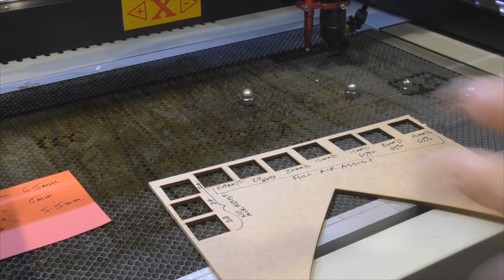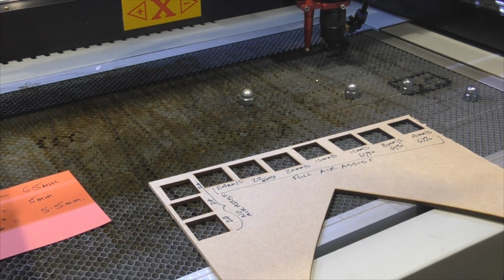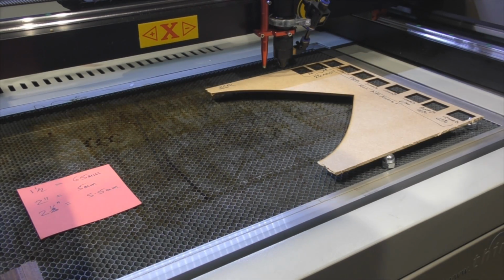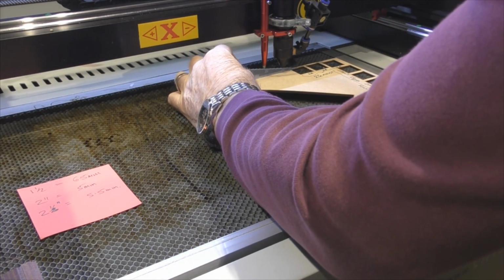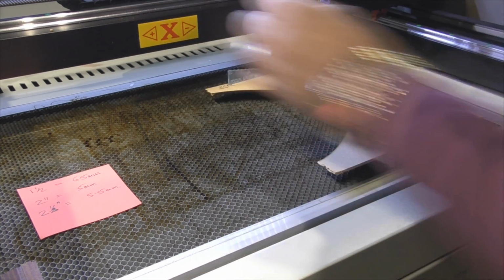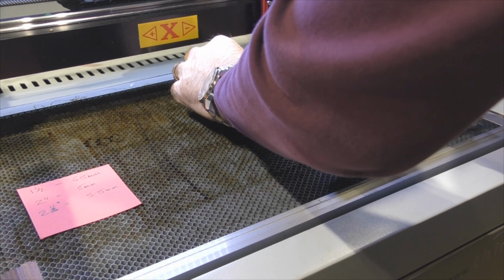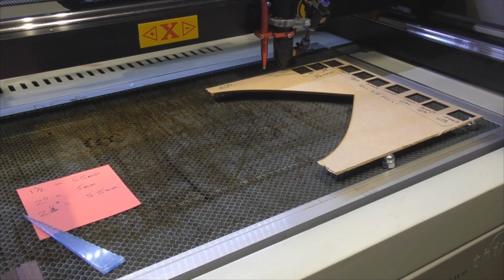So we think we've got to our maximum speed of 24 millimeters a second. Let's see if we can improve that in any way at all. We've improved the cut, we've kept speed to a maximum, and now we're going to try something else. You may remember that this was set to 5 millimeters. I'm now going to drop this down to 4 millimeters.